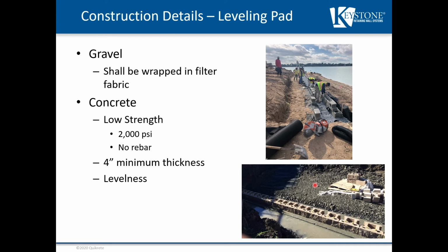Leveling pad material. So we can do either a gravel or concrete leveling pad. The gravel must be wrapped in filter fabric. As you can see here, these guys have actually utilized a crushed stone. They just kept the 3/4 inch to 3/8 inch crushed stone as part of the leveling pad. They got their fabric here and fabric back, and they're going to wrap that back up in here before they get to their next zone of material or their first layer of reinforcement.